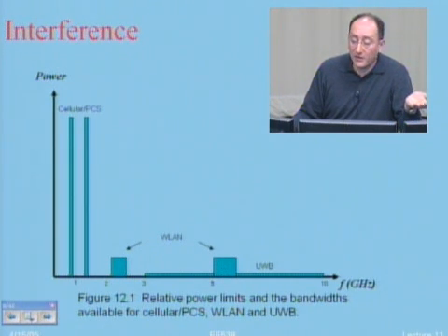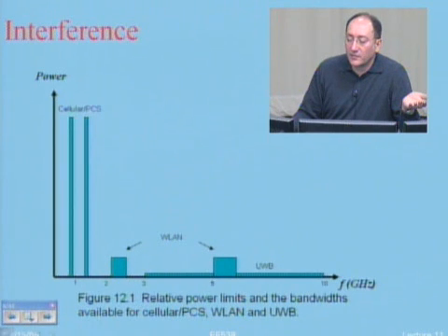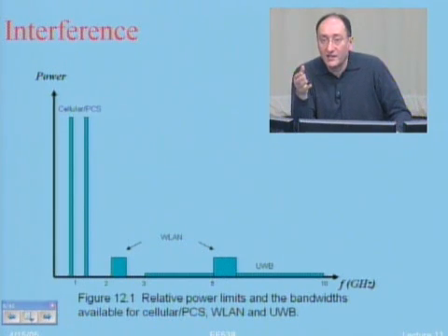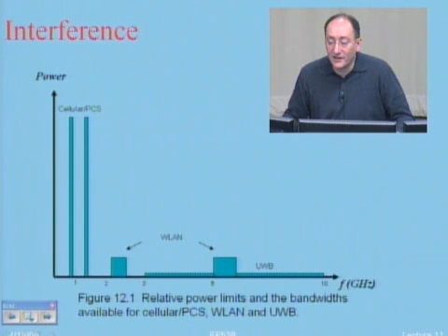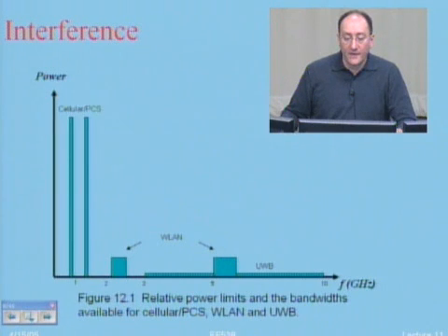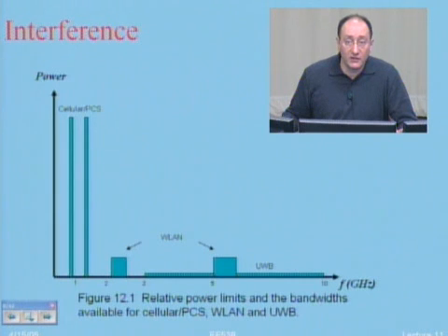And the 5 gigahertz band is which one? 802.11a, only one. And this is good to notice, because we see that the systems going to 802.15.3a try to somehow accommodate that, and they find some neat engineering tricks to somehow avoid this band. So this is an introduction about what ultra wideband is, why it is important, and why it attracted attention.